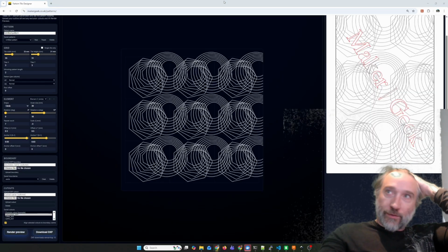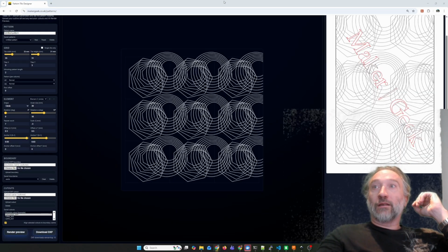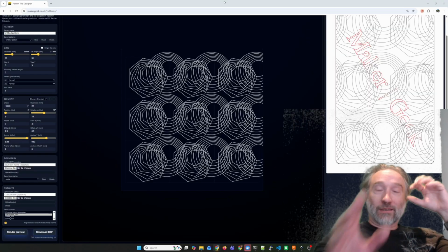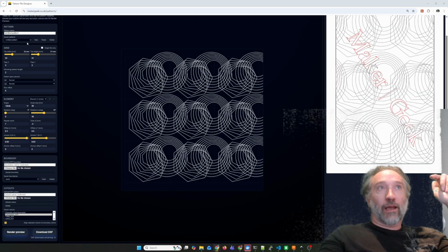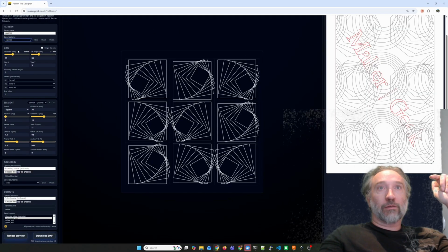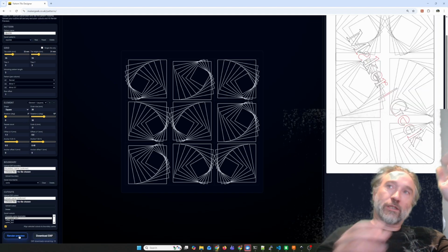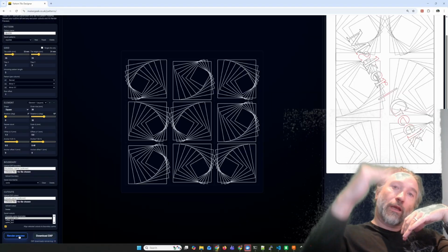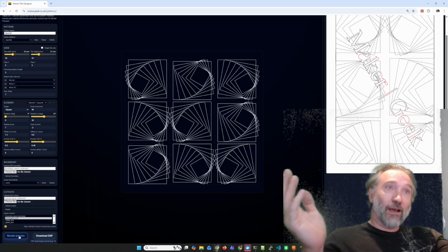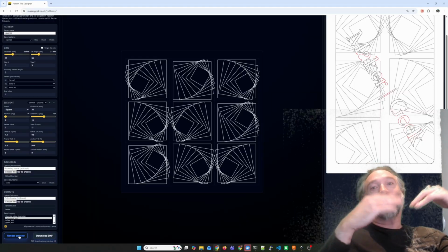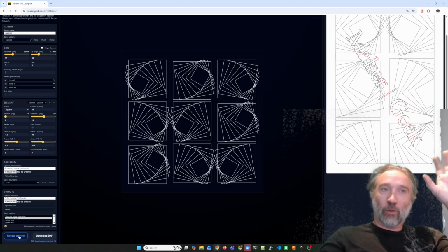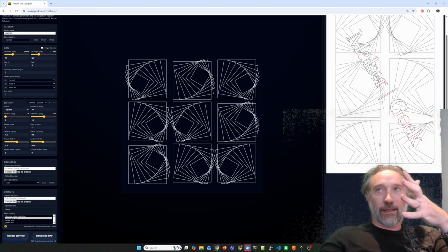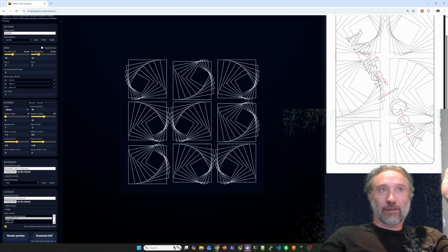Cool. So we've jumped around a little bit, but what you can see is just a different cutout, different perimeter, different cutout, same pattern. And similarly, I have a bunch of patterns that I have pre-created. So you can also quickly go through your list of patterns and switch the patterns. The idea is you can build up a library of patterns that you've designed and liked, that you keep as named things, and then you can create cutouts that you like and insets that you like, and you can combine them in whatever order you like, re-render them, and get your finished merged DXF.